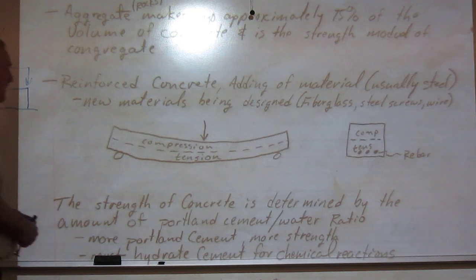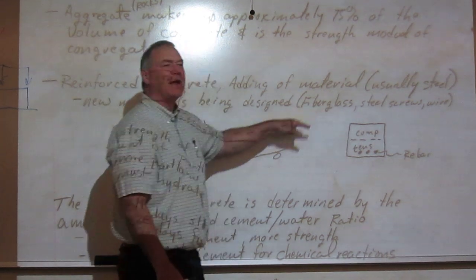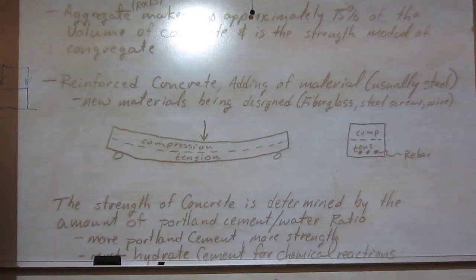Mostly you want to think of this stuff as just aesthetic crack control. When we really need the concrete to perform, we're going to rebar. Okay. Any questions on this? Yes. So that's mainly used like when you do countertops and stuff? Yes. Uh-huh. Okay. Yeah, if you're sure that slab or item will stay in compression, then you can go use this stuff. It's whenever that slab's gonna hit tension, that's a different story.